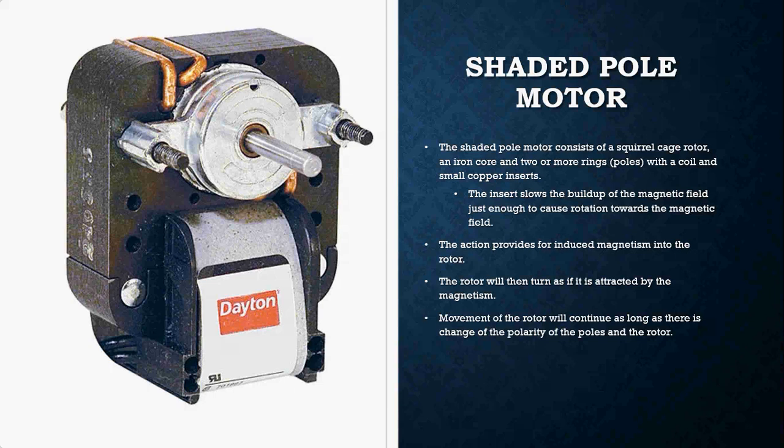Okay, the insert slows the buildup of the magnetic field just enough to cause rotation towards the magnetic field. The action provides for induced magnetism into the rotor, and then the rotor will turn as if it is attracted by the magnetism. A movement of the rotor will continue as long as there is change of polarity of the poles and the rotor. Now, what's really nice about shaded pole motors is that they are actually reversible. You can change the rotation of a shaded pole motor.